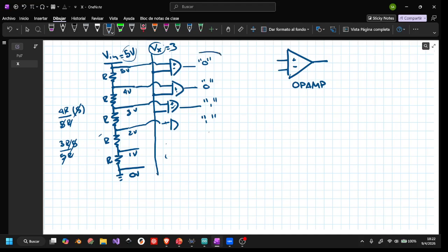So whatever number, now we have a code in binary that we can send to our microcontroller, right? It's called parallel because we are checking all the bits at the same time, right? We are running that in parallel. So this is really fast because we can do it in no time, right? Op-amps are really, really fast. We have the advantage, and the disadvantage, that it is not so precise.